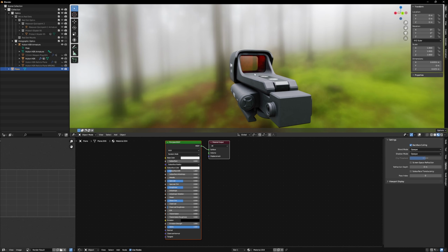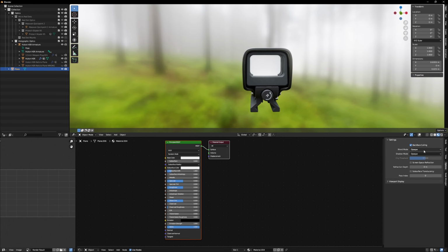So that's very important. The other settings that we need to change are the blend mode, because we're going to be working with transparency. So we can't use opaque. I don't recommend using alpha clip. It does still technically work, but it's just a bad way to do transparency in Eevee. So I never recommend using that. Your only two options are really alpha hash and alpha blend. And that's just going to come down to personal preference, because they both kind of have their positives and their negatives.